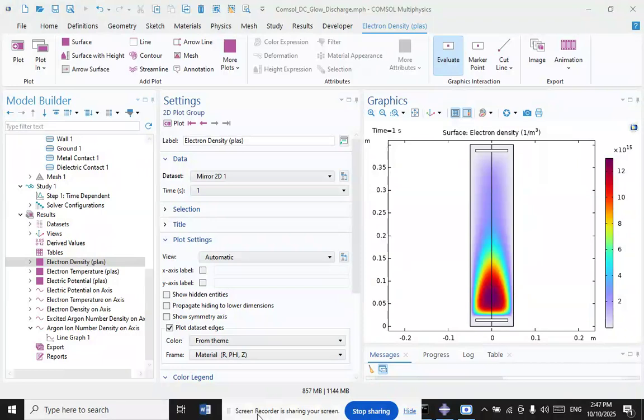In an arc discharge, electrons leave the cathode by thermionic emission and field emission, and the gas is ionized by thermal means. Below the breakdown voltage, there is little to no glow, and the electric field is uniform. When the electric field increases enough to cause ionization, the Townsend discharge starts. When a glow discharge develops, the electric field is considerably modified by the presence of positive ions. The field is concentrated near the cathode.